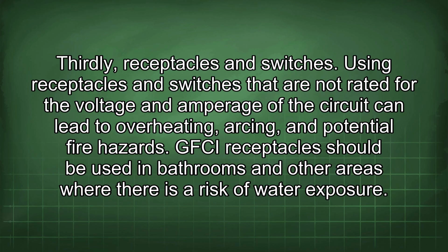Thirdly, receptacles and switches. Using receptacles and switches that are not rated for the voltage and amperage of the circuit can lead to overheating, arcing, and potential fire hazards. GFCI receptacles should be used in bathrooms and other areas where there is a risk of water exposure.